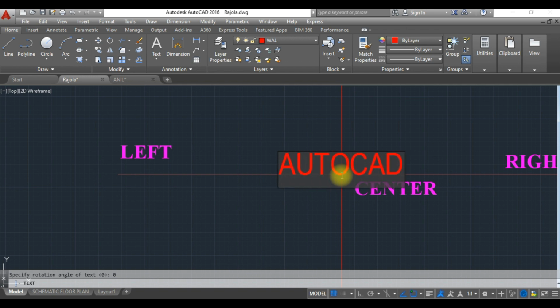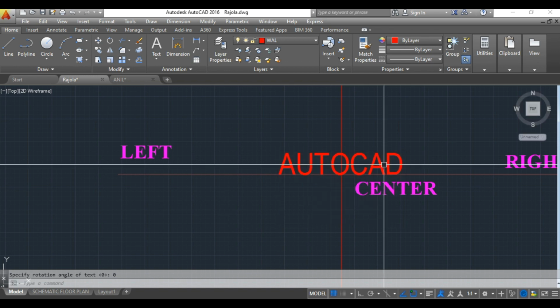R2CAD. So what it is doing is splitting the text into two equal halves. Half of this text will be on the left-hand side and half on the right-hand side. I took this intersection so you get clear information about how the center command works. Center means the alphabet center, half left and half right. If I hit enter, it will come to the next line. If you don't want to write on the next line, just hit enter once again and it will come out of the command.